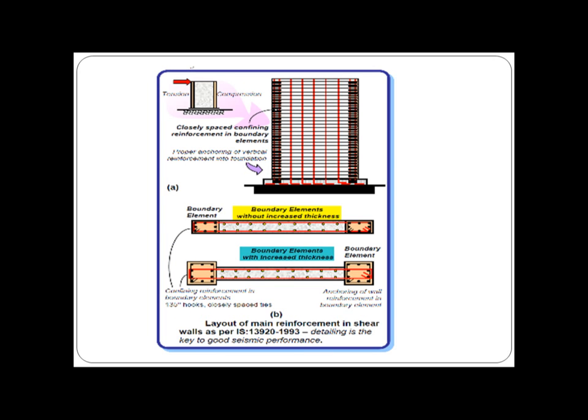And this is the picture depicting the reinforcement detailing of a shear wall, which is nothing but a double mesh. Depending upon the thickness of the wall, the reinforcement can be provided in double layer or in single layers. And when the edges are not sufficient to take the allowable compressive stress, we need to add stiffened edges, which are nothing but boundary elements. These boundary elements can be of the same thickness as the wall, or they can be enlarged ends. Normally we place shear walls between columns, so those columns act as the boundary elements or the stiffened edges.